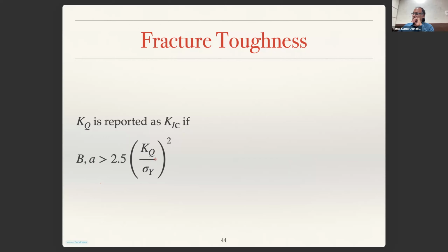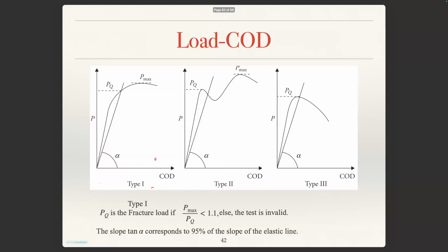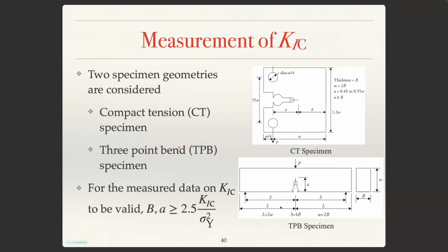Any questions here? Sir, how is this 3-point bending test initiating a mode 1? Actually, the load directions are different. The load direction is different, but if you are loading like this, ahead of the crack tip it will experience an axial stress, right? Sigma 11. It's a bending problem, no? Okay. It's an axial stress that is locally experienced. That axial stress is what is causing this crack to open, isn't it? Okay.